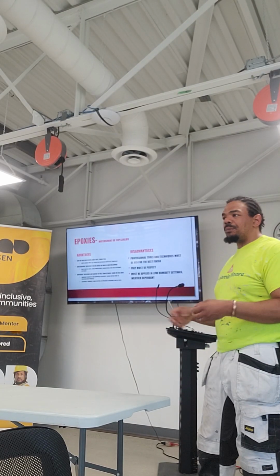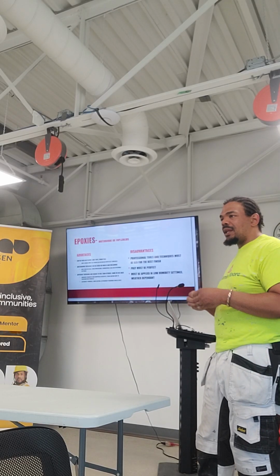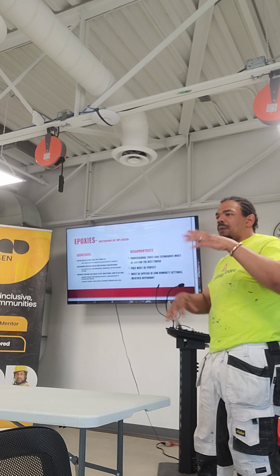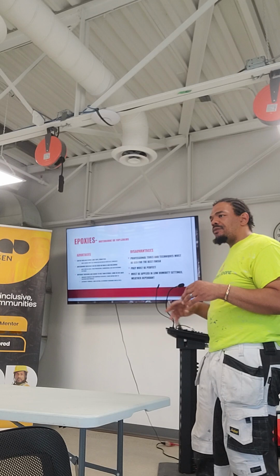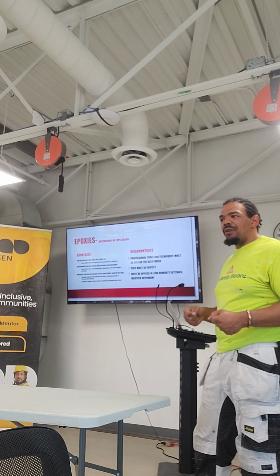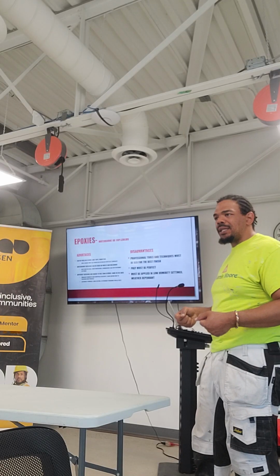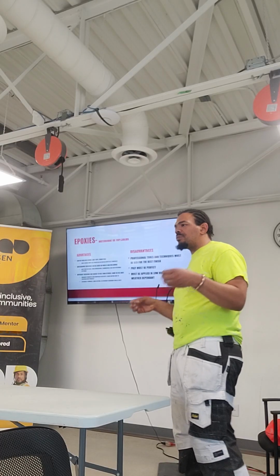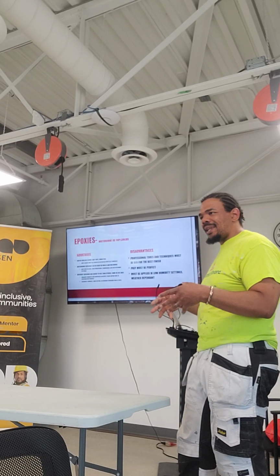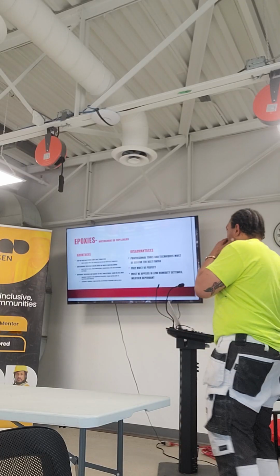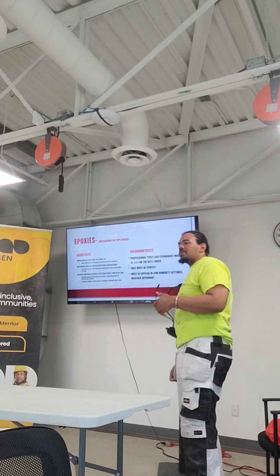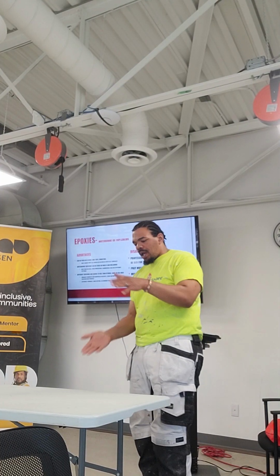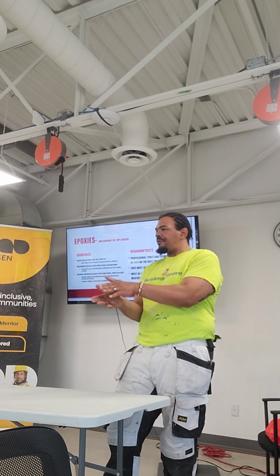So it's just a lot of polymers and a lot of resins, and they pack it in, and then they put a very minuscule amount of solvent in there, just to make it able to move and make it viscous. But if you've ever used epoxy, it's way heavier than normal paints. Epoxies and lacquers are some of the heavier paints because there are so many chemicals and additives in them. It's extremely heavy. Epoxies can be used on floors, and on tabletops; they make tables with epoxy. You can pour it into a surface, and you can get epoxy to pour up to 1.5 inches thick per pour.